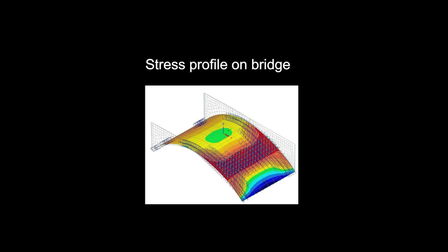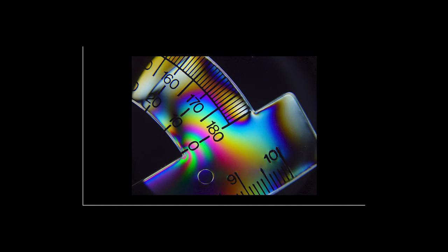Since we need to find the points where fractures can occur, we'll use the yield criterion, and for that we need to find the different stress transformations at different angles. Otherwise, we might make mistakes in our calculations, resulting in failure. So now we'll see the stress profile in this image. As we can see here, there are different stresses at different angles and different positions.